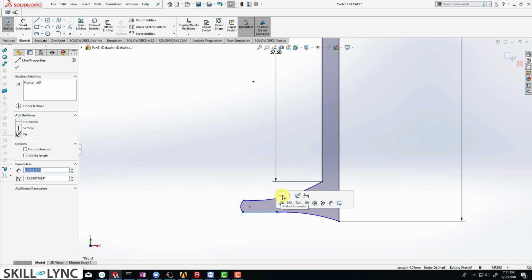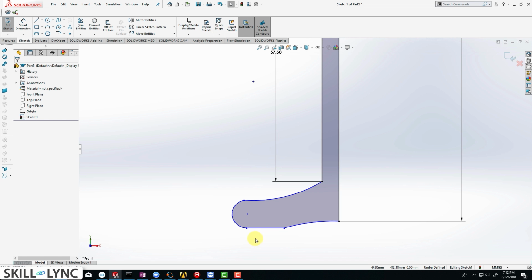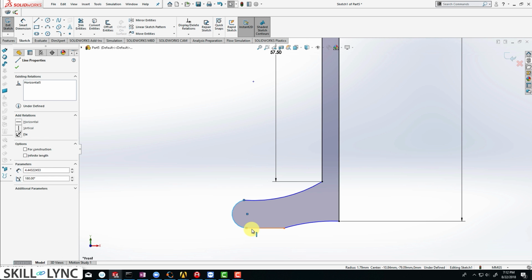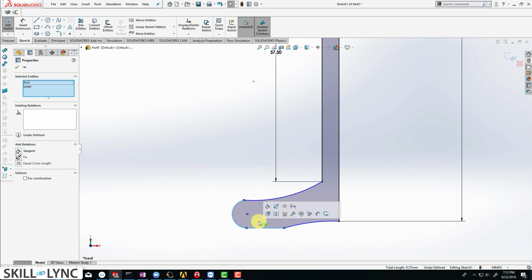And then just drag this out. Looks like the shape is kind of funny, so we need to select this particular point and drag it out. We'll assign the exact dimensions shortly. So let's just click on this particular arc. It looks like it's currently not tangent to this line, so let's select this line and click on make tangent.